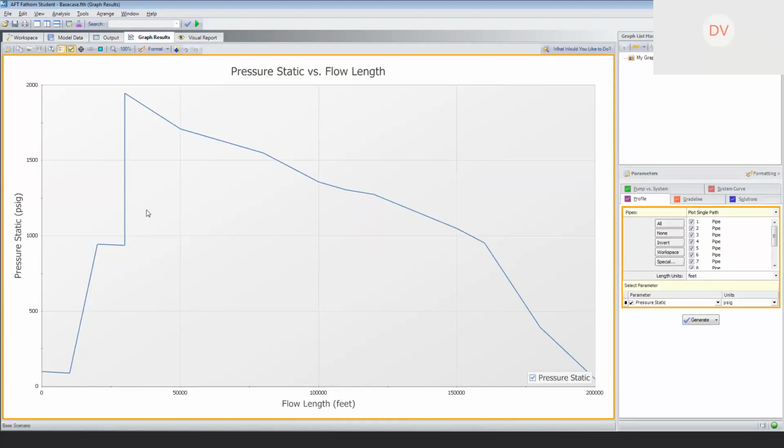If we tried to design this entire route based on the 1900 psi, then there's a lot of wasted steel. So your task will be to figure out how much pipe you want to order at a certain pressure rating. As you can see, there will be some pipe that can be at a lower pressure rating, so that's for you to determine, and it will be a large amount of the variety between each of the teams.